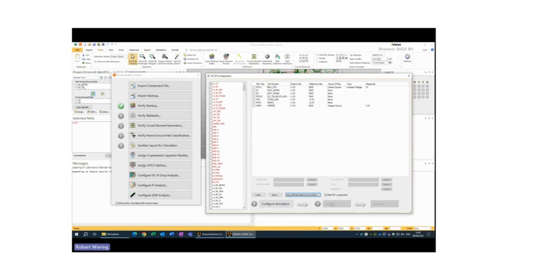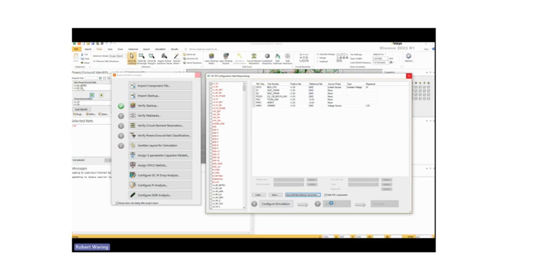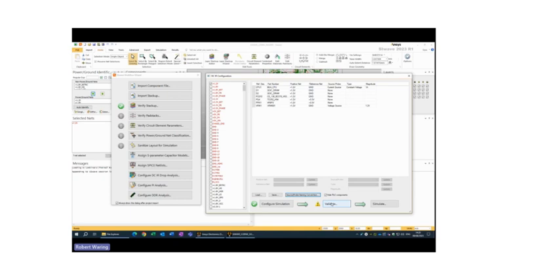What validate does is check that you've not made any obvious mistakes in your setup, to make sure that whatever's here is actually a number. It will also go through your geometry to make sure there isn't anything that would make the mesh hard to generate, such as planes that are crossing over each other when they shouldn't. Brilliant, so we've got no problems. I know that because I did it before.